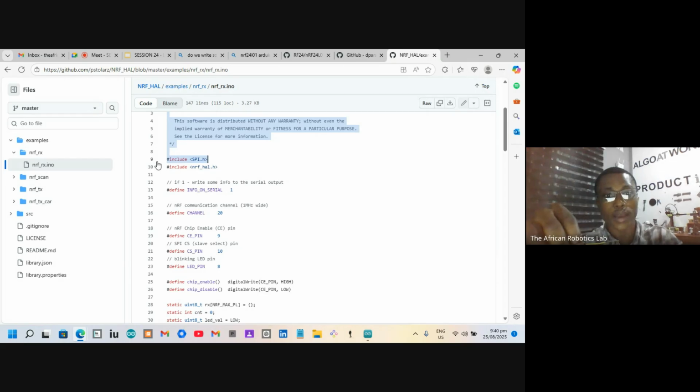You can find serial data and serial clock on this one. No, this is SPI. SPI uses four pins. So we have the MOSI pin, we have the MISO pin, we have chip select or slave select, and then finally we have the serial clock, SCK. So there are those four pins on there. So you just connect it to your microcontroller, together with the other pins, and then that's it.